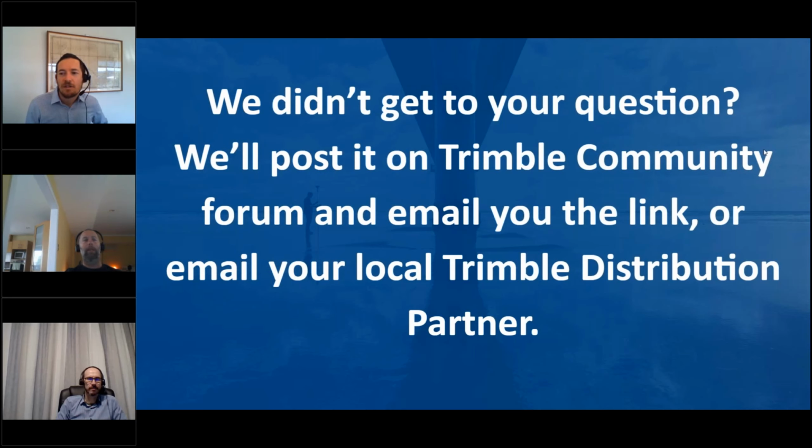But if you have an NZ geoid up there in Auckland and it's a subgrid or it's got a slightly different name. Okay, so if you have a slightly different geoid on the controller that's used by TBC, even though it could be NZ Geoid 16, which I'm guessing that you're using, but maybe it's a localized one, the names must match. So you're going to have to get that geoid from the controller into Trimble Business Center, and then the as-staked points will be convertible.